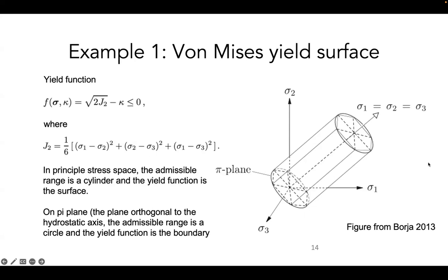But one thing that could be quite interesting is that it depends on how I parameterize the yield surface, meaning how I write the yield surface, with different levels of complexity. For J2 plasticity, the smartest choice is to write it in terms of J2 because I just have one dimension. I just need to control J2 to be smaller than the yield stress, and that's it. Another choice is to use the principal stresses. Another choice is to write the entire stress components. They're all equally valid.